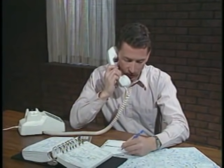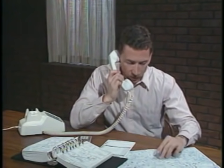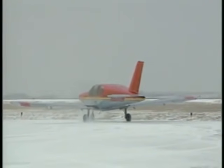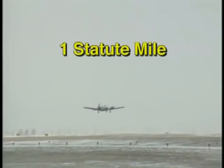By regulation, before any IFR flight, you must check the en route weather and the weather at your destination and departure airports. For commercial flights operating under Part 121, 125, or 135 of the Federal Aviation Regulations, certain visibility requirements must be met before a takeoff is allowed. While these minimums are not required for flights conducted under Part 91, they are good guidelines for you to follow. For aircraft with 1 or 2 engines, the standard visibility minimums for takeoff are 1 statute mile.